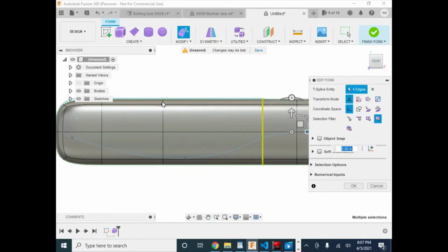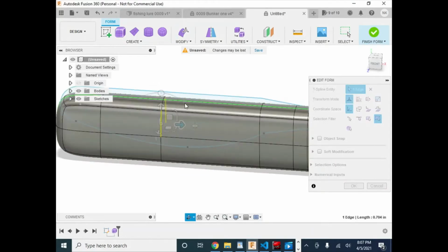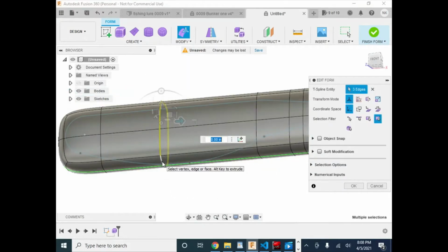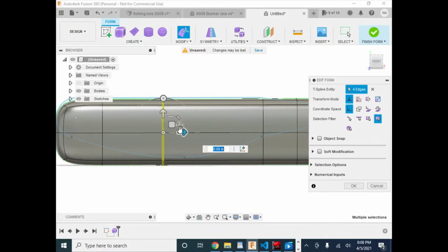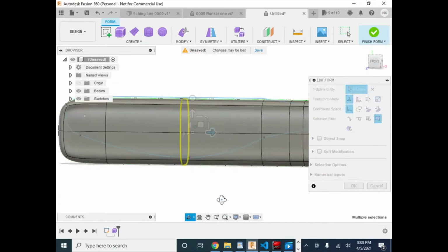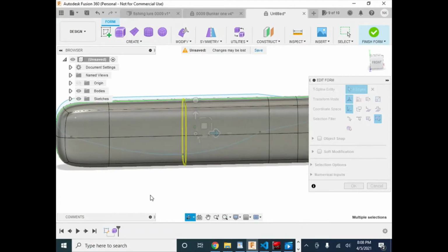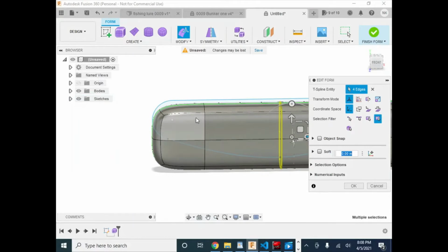This one in the middle, what we're going to do is try to... Oh, that clicked on the point. So be careful. You do want to see the line, not the points. We don't want to get there yet. And then we'll click on this one. So this is going to be my center point. Again, it shifts things, so we might have to shift that back, but we'll say that's pretty much good for right now. And then I want that sweep to come up to the nose.